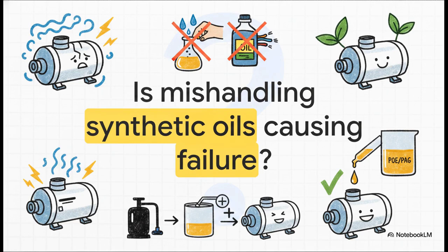So I want to leave you with this final thought to ponder today. Considering just how incredibly sensitive modern PoE and PAG oils are to moisture and electrical conductivity, is your daily handling of these lubricants secretly setting up your next catastrophic compressor failure? Respect the chemistry, pull a really deep vacuum, match your oils perfectly, and I promise you, your systems are going to thrive.